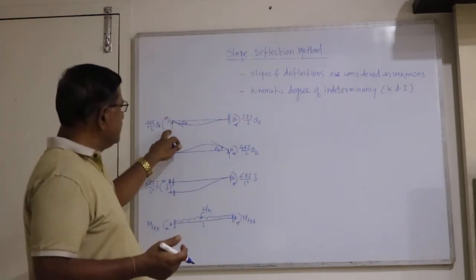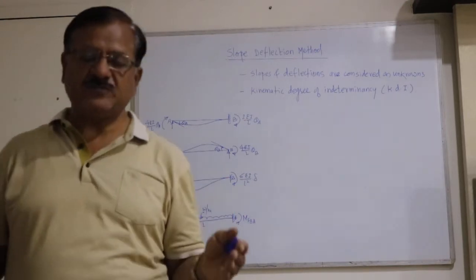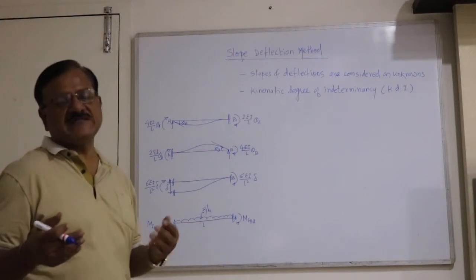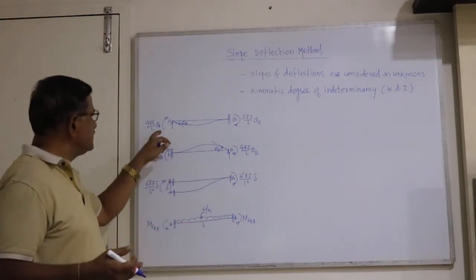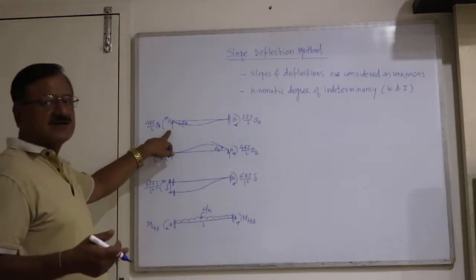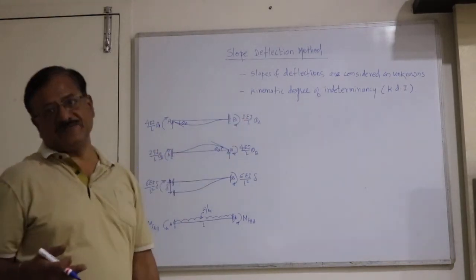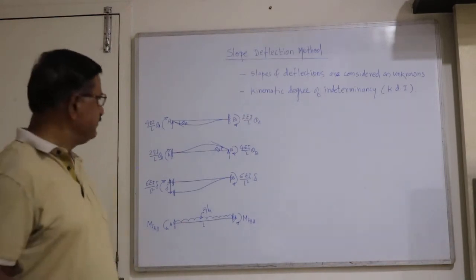That means if a beam AB is a fixed beam or an intermediate span of a continuous beam, and end A undergoes a rotation theta A, then the fixed end moment developed at the end where the rotation occurs is 4 EI by L theta A, and at the other end half of that, 2 EI upon L theta A, with the same sign.